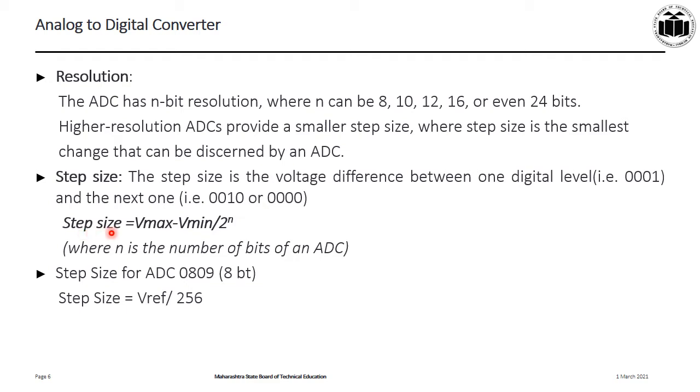Formula for step size is equal to Vmax minus Vmin divided by 2 raised to n, where n is the number of bits in an ADC. Step size for ADC 0809 can be given as V reference divided by 256, as 0809 is an 8-bit ADC.